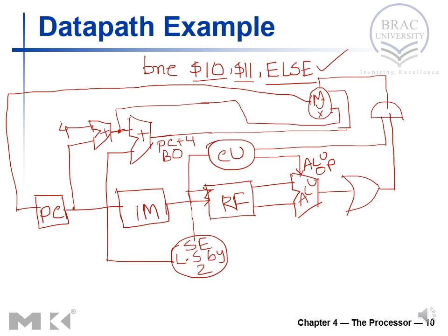Now this is the diagram of the data path for this instruction. Now I shall give you the bit length of each line. This one would be 32 bits, and this one is 32 bit, and this is a 16 bit value that is coming in. These two are 32 bits. This one is 32 bit, and the output is 1 bit, and this control unit generates the BNE instruction signal, which is 1.